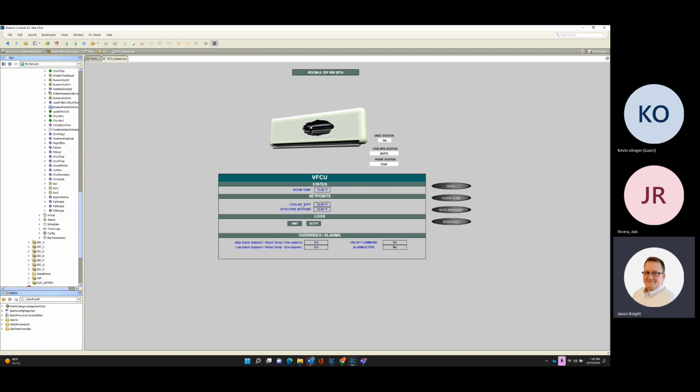Yeah, a lot of the facilities guys for the school districts get the Mitsubishi units that have the wireless remote. You have to disable the remote, physically take the batteries out of the remote, to let the DDC be able to work with it. I was just thanking God we didn't get those on here, because that's a nightmare.